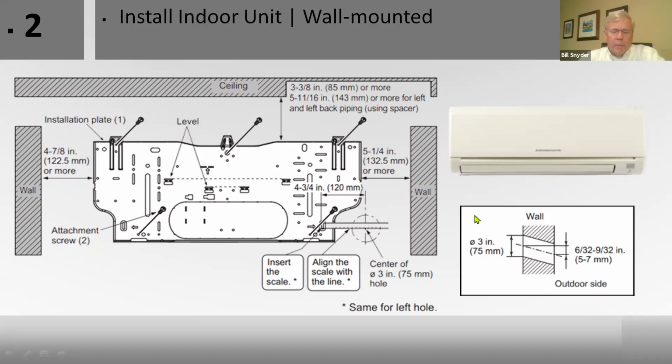But let me warn you, all of the electronics are in this side, and if you have to do the service, you have to pull this off and get into the side. So I would never mount this thing 5 inches away from a wall. That's just not enough room to do service. So you just have to consider that.